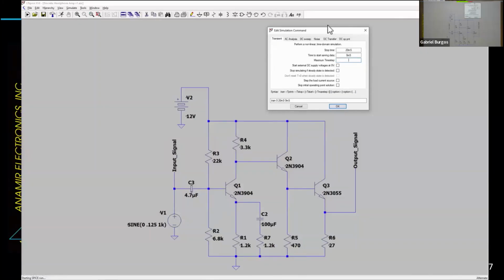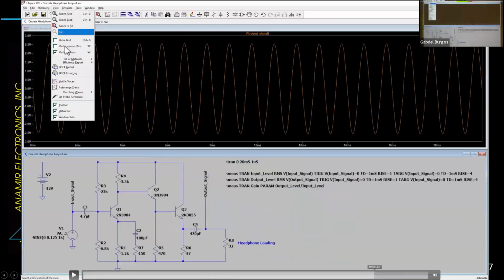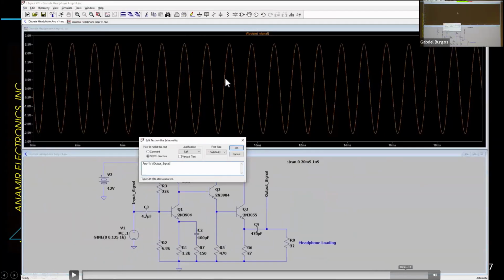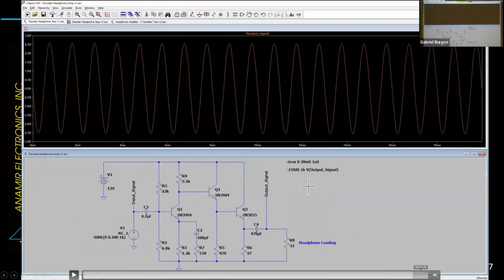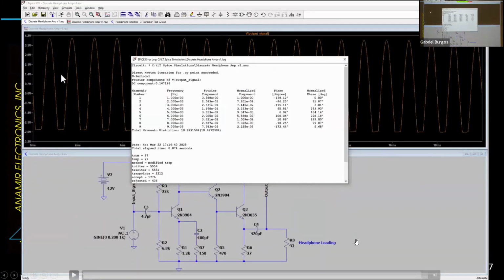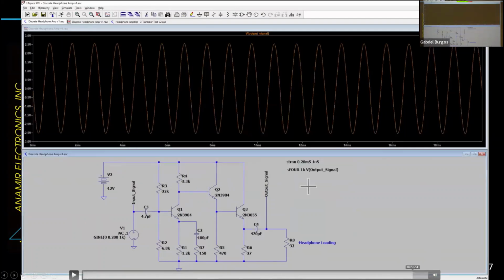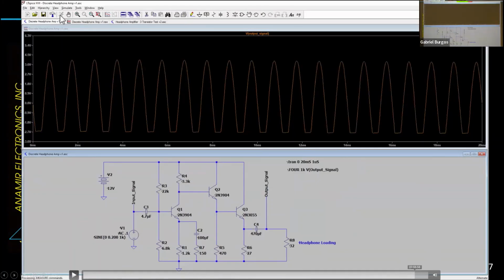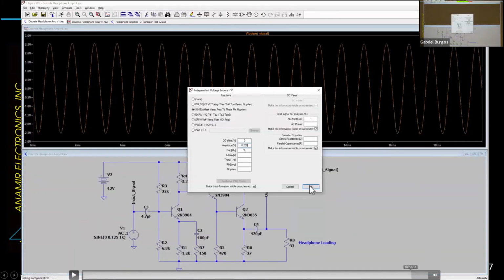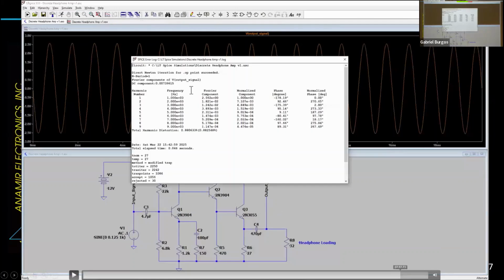So this one, I remember we had like 0.06% distortion with the IC chip. This one here, when you do the distortion measurement, came out to be, well, that was after I overloaded it. I put more than a 125 millivolt signal in there. So this one's 0.86%.